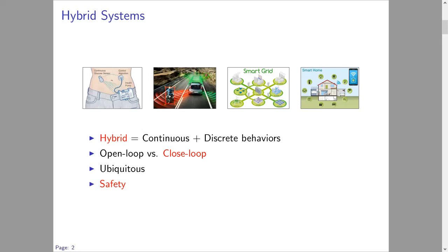A closed loop system is based on system state to iteratively progress towards a desired outcome. For example, a patient with diabetes can benefit from a hybrid closed-loop insulin delivery device. At each cycle, it detects the patient's blood glucose level and sends it to the controller. The controller uses such information to predict how much insulin should be injected and asks the insulin pump to inject that amount to keep the patient's blood glucose level in a safe range. Then it moves on to the next cycle.